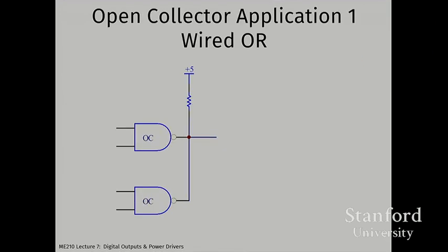One interesting thing that might be useful, I'd say we throw it in here just to make the point, but I doubt you'll need much of it. But if you have groups of open collector devices, you can connect all of them together, and the way they'll operate together is as an OR. So if A or B is low, then the output goes low.